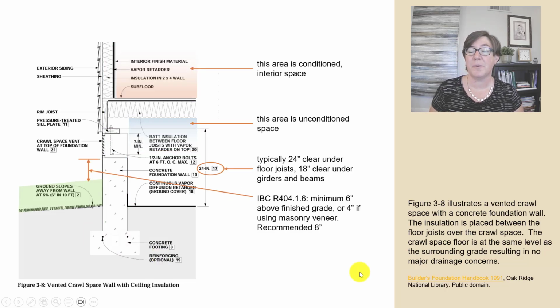Here's a couple more notes on this crawl space foundation detail. First of all, notice we've got this area up here. It's conditioned interior space. All right, this is where people live. Underneath, we now have unconditioned space. So this is open to the exterior, right? It's not interior livable space at all. And notice that we have added insulation right here so that we don't have heat flowing from inside to outside.